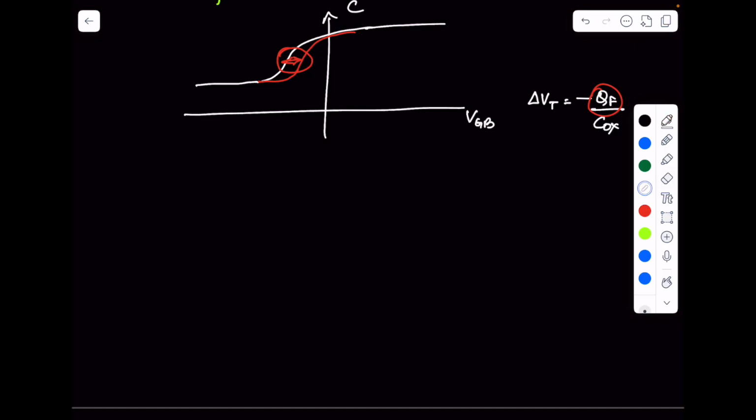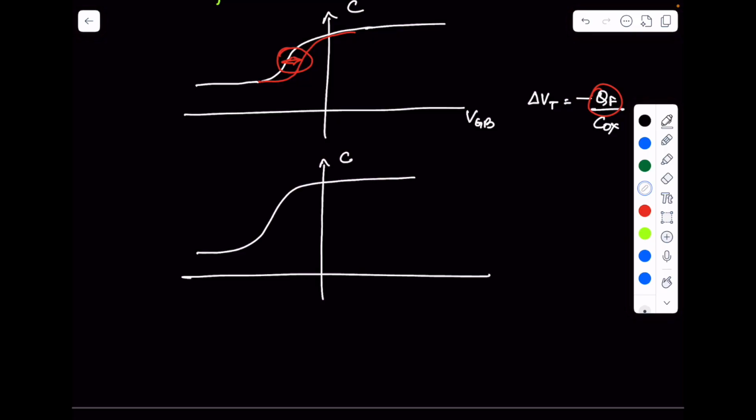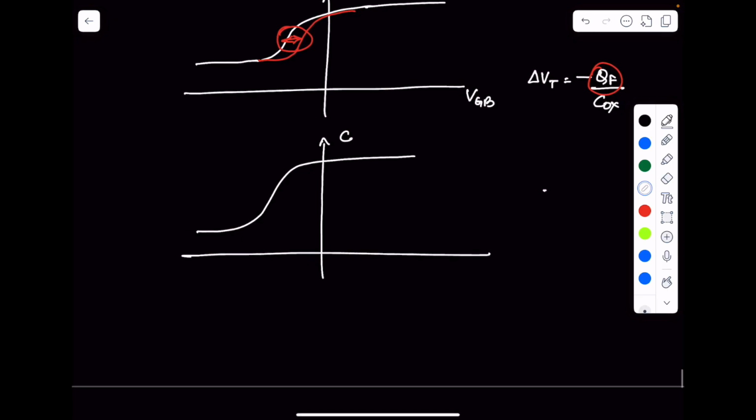Now let's go to the third part of the question, which asks, a gettering is performed so that 10% of the mobile ions from the top of the oxide are eliminated. So remember, the oxide has a bunch of charge. This is your gate, this is your silicon, and you have oxide charge, mobile charge, present all over, be it positive or negative.